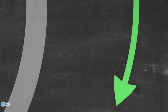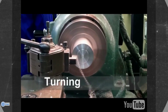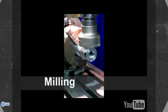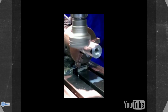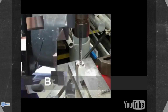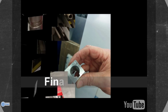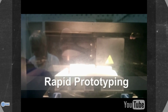The manufacturing process was split into 2 main parts, the hub and the blades and cone. The first step in creating the hub was the turning process, where the lathe was used to produce a circular shape. Material was progressively removed as the aluminium block rotated. Then milling was performed so as to achieve the desired square shape of our hub. Following this, threading was done so that the cone could be firmly secured to the hub. The final step was to broach a keyway through the hub to ensure the wind turbine will be locked together with the test rig. The blades and the cone were manufactured using the 3D rapid prototyping method, and the material used was ABS plastic.